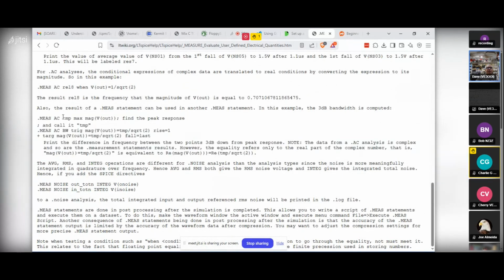And you see it's .measure AC, and that's just a variable name, temp. And you're saying measure what the maximum voltage is. Then it says measure BW, as you said, that's just a holder, just a variable. You could call that shift. It doesn't matter. And then here's what you need to go and run. It says how to run it. But notice they both have the AC. You're right. Sorry. Go ahead. No, that's it.